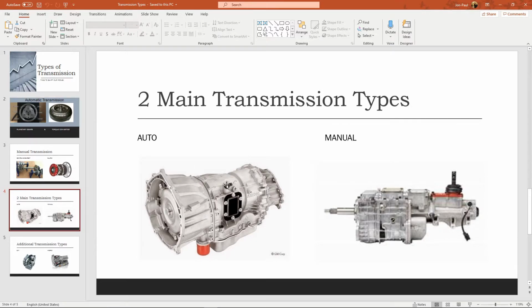This automatic is shorter, but much bulkier than this manual. This one is longer, but thinner. The automatic transmission is full of fluid and is going to be much heavier than this manual. How we tell it to shift on both of these are going to be similar, either a linkage or some cables. So whichever way you slice it, you're going to have those components. The thing about this automatic having fluid, though, is that fluid has to be changed regularly, otherwise you have problems. The manual transmission will last much longer and doesn't require nearly as much maintenance.